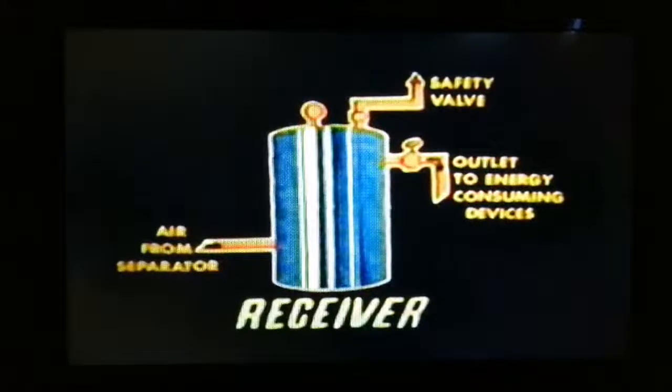After air leaves the water and oil separator, it enters the receiver. Every compressor must have an air receiver. This is a tank into which the compressed air is discharged from the compressor. They act as storage capacity during intervals when demand exceeds the capacity of the compressor, and fittings should include a pressure gauge and a safety valve.